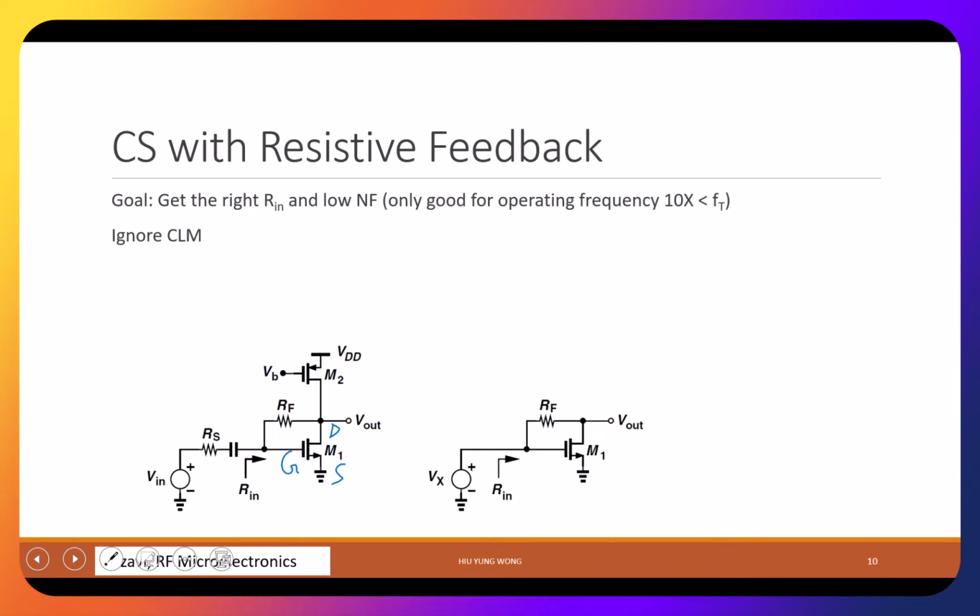But now it is small. We assume we can ignore it, right? In the real circuit simulation, you will take into account. But we deliberately put an RF here. We bias this one with a current source, right? With constant bias. So PMOS, VGS, W on L mu C ox divided by 2 VGS minus VT squared. That is the current going out. It is in saturation. This is just like a current source.